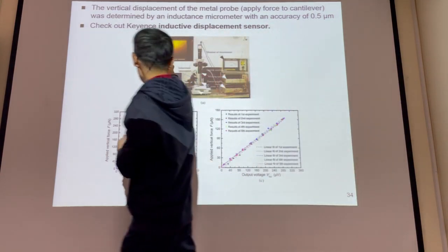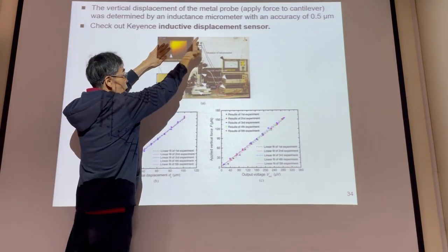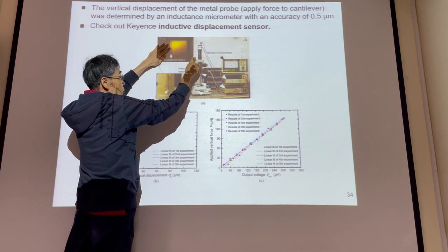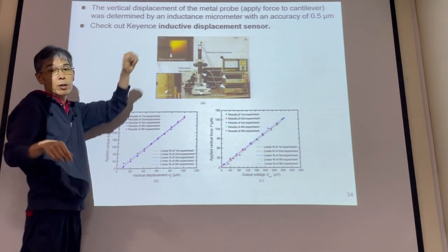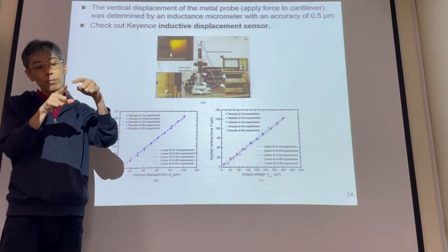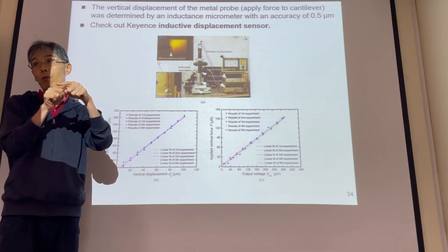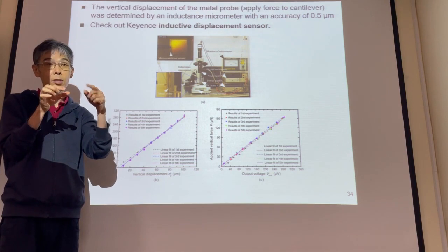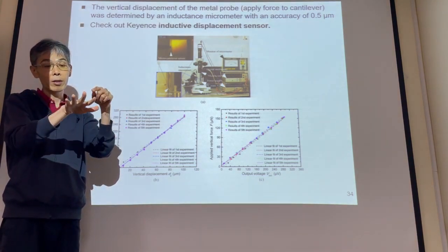So you could have a theory. In order to measure the resistance, you need one wire connection and another wire connection. Two wires go in. Wire has resistance. If the wire resistance is much larger than the piezoresistance, it doesn't make sense. And also, we have the pad.